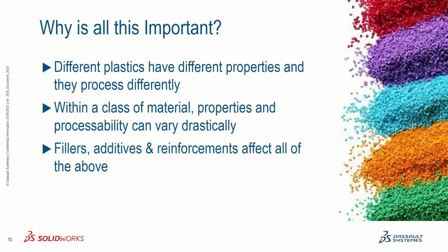Whereas the same car, when it comes to tail lamps, you would be using, say, for example, an acrylic, because acrylic has as good optical properties as polycarbonate, but they're not as high when it comes to impact strength.